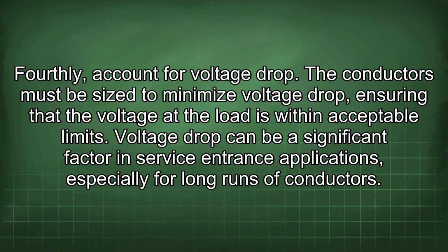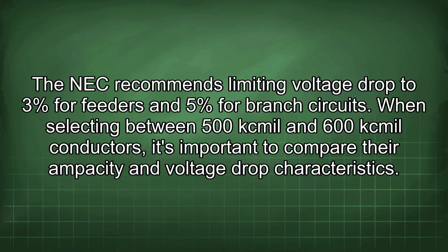The conductors must be sized to minimize voltage drop, ensuring that the voltage at the load is within acceptable limits. Voltage drop can be a significant factor in service entrance applications, especially for long runs of conductors. The NEC recommends limiting voltage drop to 3% for feeders and 5% for branch circuits.